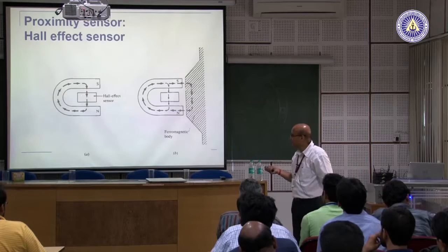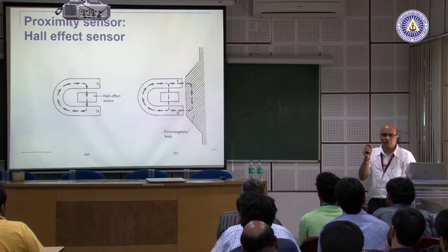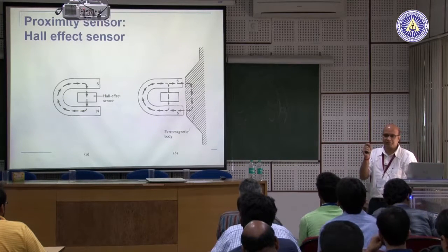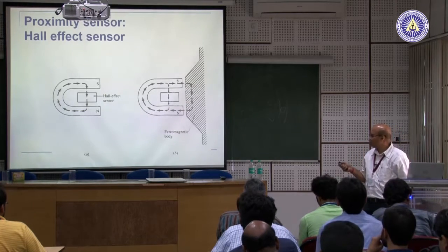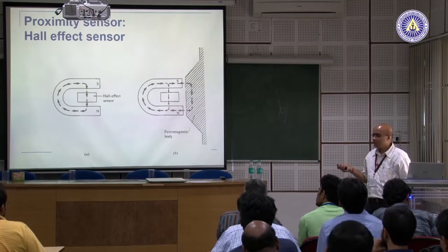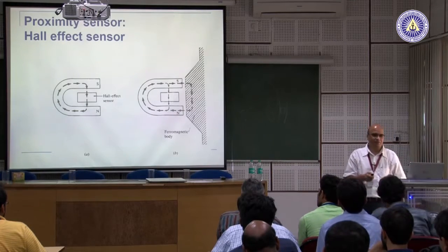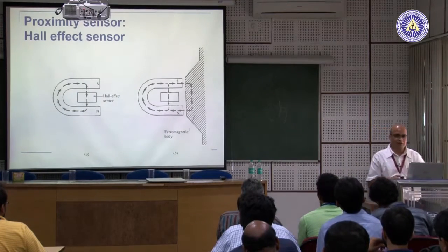This sensor is very small, very cheap. It is a MEMS sensor, about 3 millimeters or something. The working principle is very simple, the electronics is very simple. It is very rugged. It is solid state, there is nothing moving inside. So, it is very rugged, and it is extensively used.